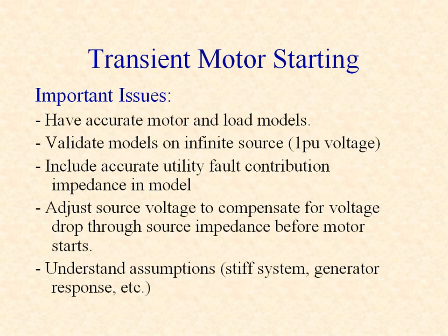For transient motor starting simulations, it's important to have accurate motor and load models. We also recommend validating the motor and load models with an infinite source and no network impedance. It's important to have accurate source fault impedance and to adjust the source voltage to compensate for the pre-start drop through the source impedance. Transient motor starting assumes a stiff power system where the source voltage and frequency are constant and where generator output is fixed.